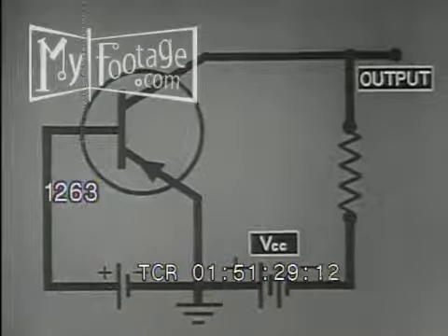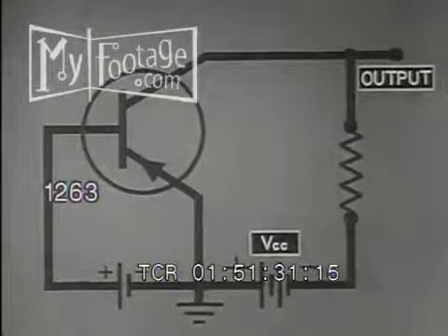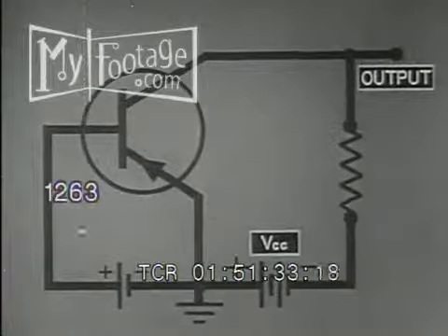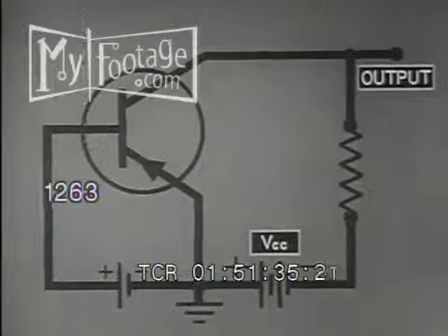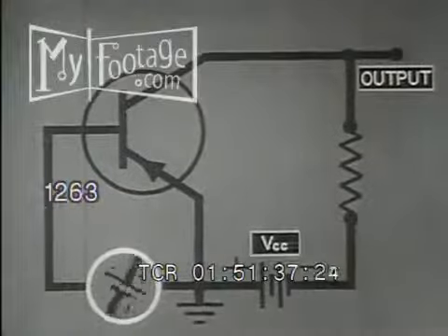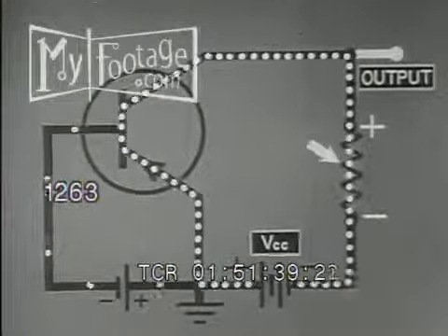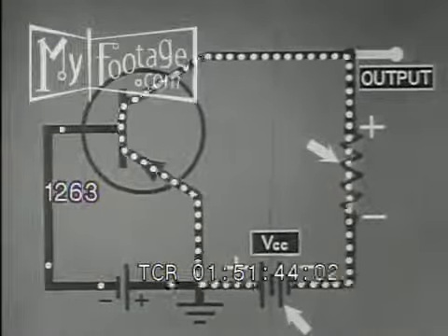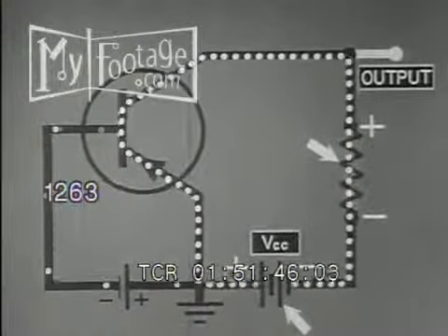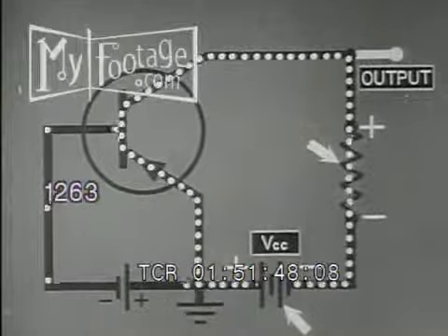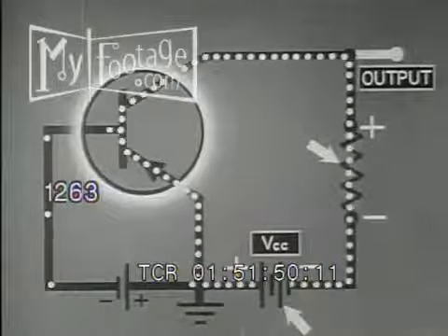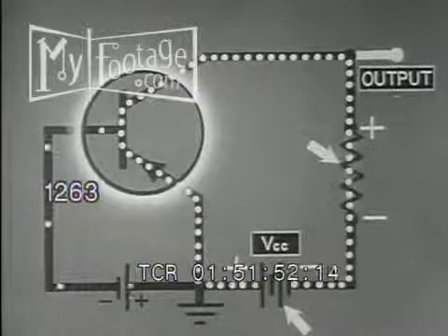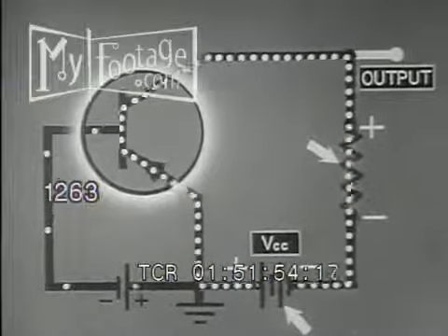Though it looks like one, this is not a common emitter amplifier. It's a direct current switch. When the switch is on, the IR drop across its load cancels the collector's reverse bias. With no voltage across the collector junction, the transistor itself uses up almost no power.